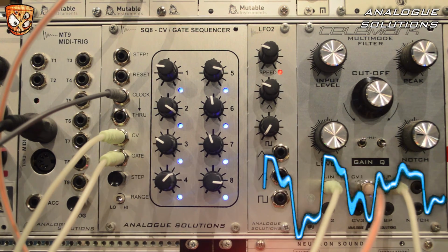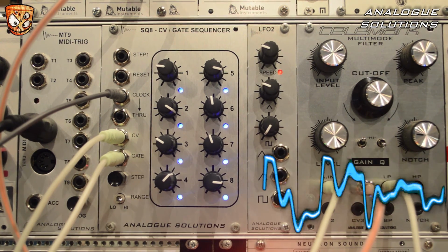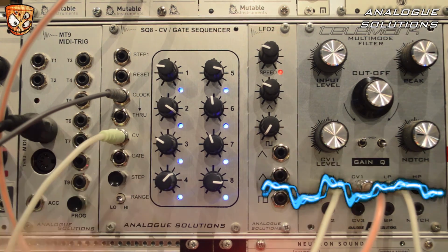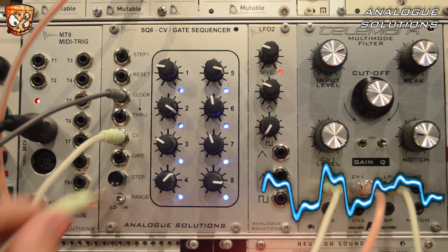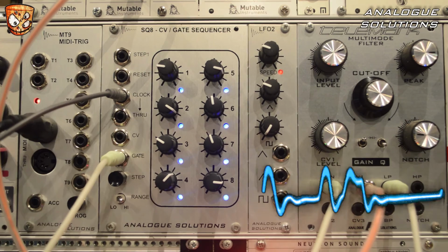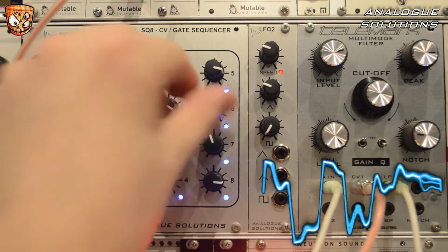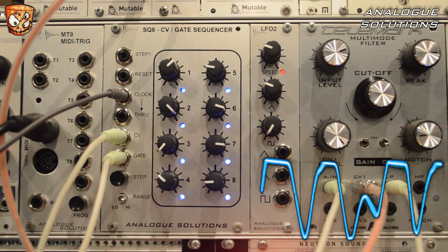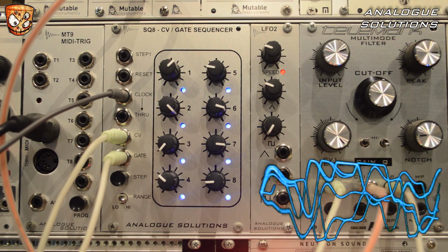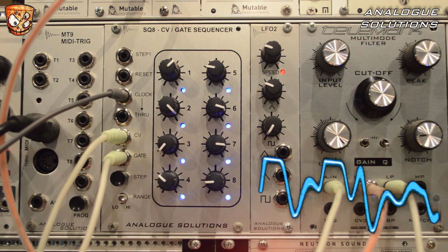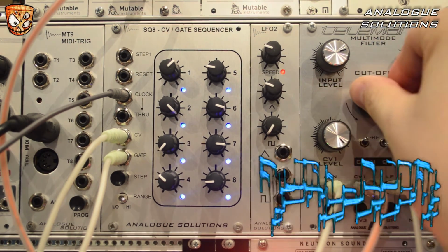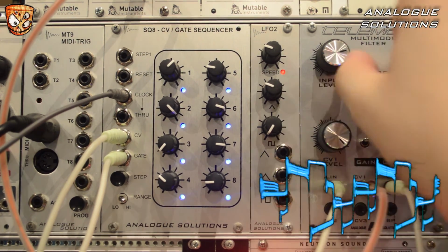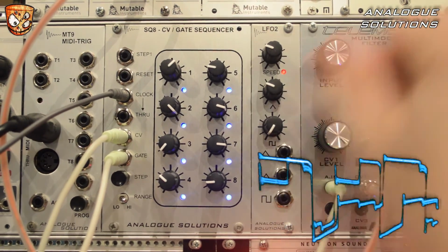So what you're hearing now is the gate output and the CV output being crossfaded. Taking the gate out, you can hear that fade to nothing, and taking the CV output, you can hear it fade to nothing as well. So I'm going to create some custom waveforms using both the gates and CVs. With a sample and hold sent to the pitch of the oscillator providing the audio rate clock, I'll then play around with the gates and CV outputs to create some custom waveforms that are going to crossfade between each other.